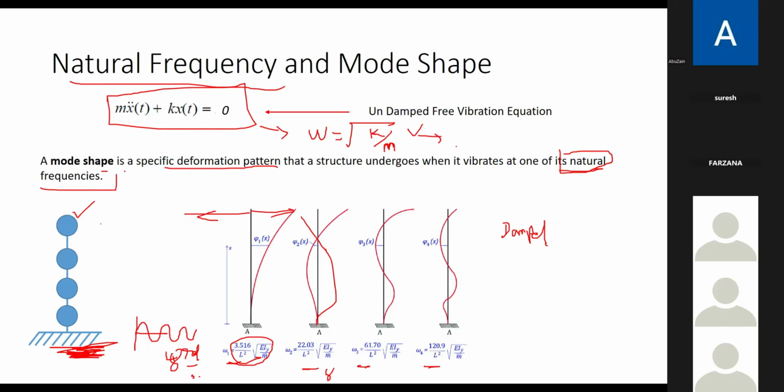So what is a mode shape? It is the deflected shape of my structure for a particular frequency. For a particular frequency, let's say this is a natural mode shape.